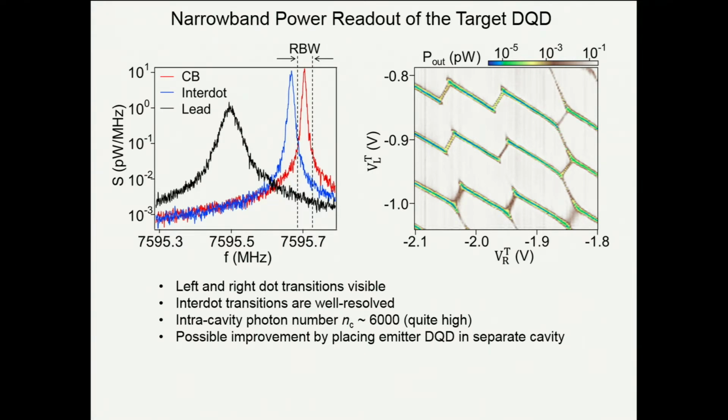So I don't know if that was a clear explanation or not, but you can measure the transitions, and the transition amplitude depends on the gammas, the rates in the problem relative to the drive frequency. And so here, they're nicely matched. But for this right dot transition, if you were to extrapolate between this triple point and this one, you'd expect to see a line, but we don't see a line. And that's because this rate is too slow. But as we go to more positive voltages, that rate becomes larger. And over here, you can see it.